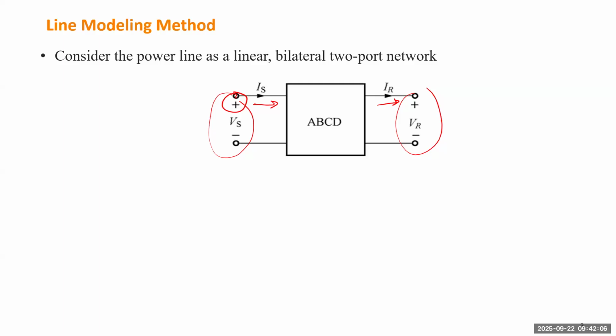depends on calculation. If you remember how we use the phasor diagram to determine the angle difference between the voltage and current phasor, then we can decide the signs for P and Q, right? So we have to draw P and Q in the complex plane to know whether this equipment is really an active source or reactive load, or active load or reactive source, right?